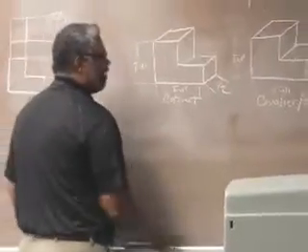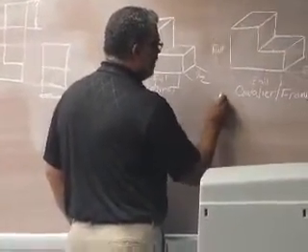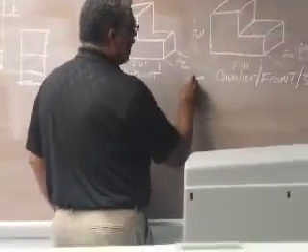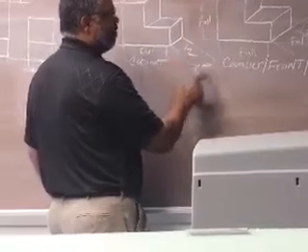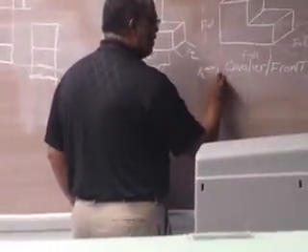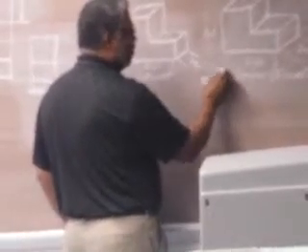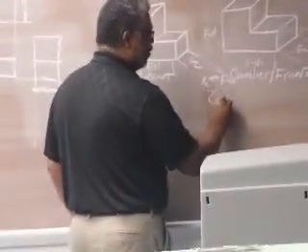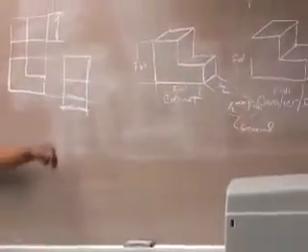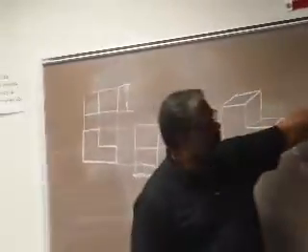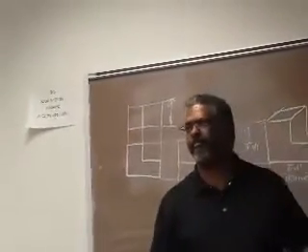If I make this distance between half, because half is a cabinet and the full distance is a cavalier, then that's a general oblique. That gives you a little flexibility, because sometimes when you go back the full distance, it looks distorted. That's a problem with obliques.